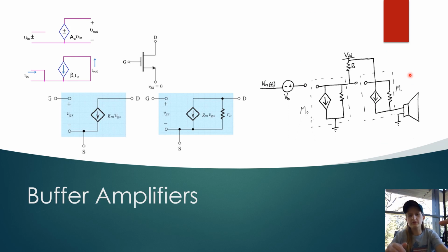The buffer prevents the second circuit from loading the first circuit's current excessively and interfering with its desired operation. So in this case, you would get crappier sound amplification. In an ideal current buffer, in the diagram, the output impedance is infinite, and with an ideal current source, the input impedance would be 0, or act as a short circuit.